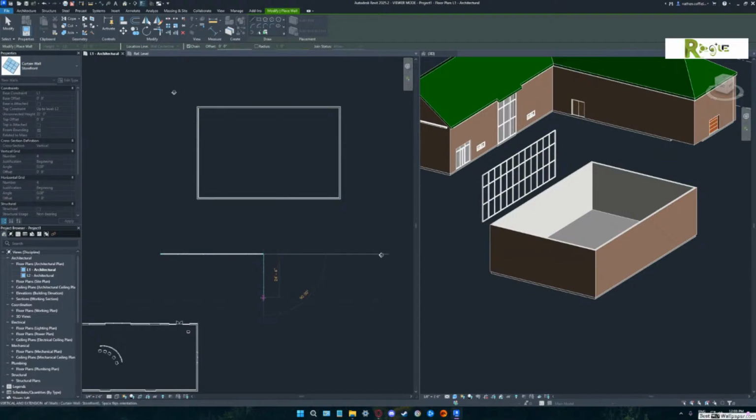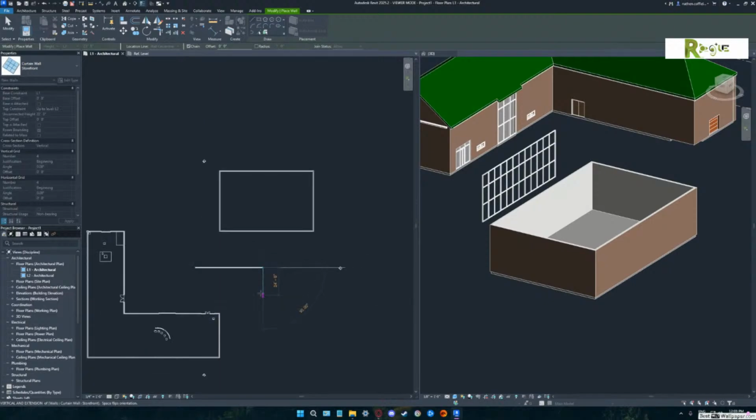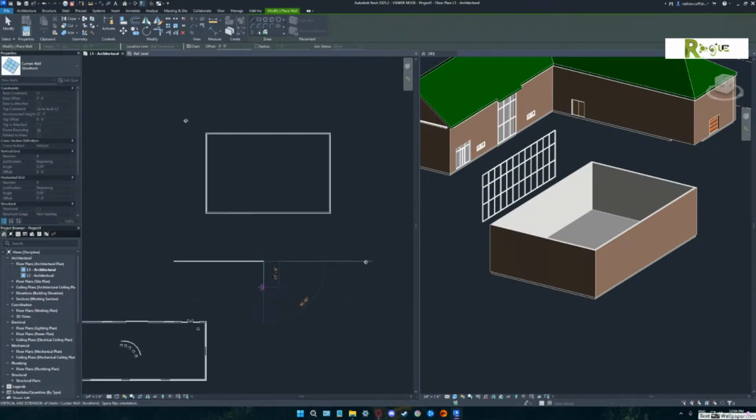That's fine. Notice how it, other than snapping to a line, come off that line. Notice how it's 23. If you move up a little bit more, it'll be 23'6", then 22, then 22'6". So if you zoom out a little bit, roll your wheel a little bit, you're going to find now, you see what it's doing? Every 4 feet. You with me? Yeah. That's all related to what was in that snap dialogue that we just showed you.